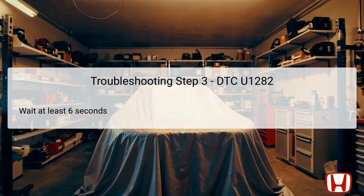In the third troubleshooting step for DTC U1282, it is important to wait for at least 6 seconds after switching the ignition back to on. This waiting period allows the onboard vehicle systems adequate time to initialize and establish all necessary communications. Swiftly moving on to the next checks without this pause can result in incomplete system readiness, which could yield misleading results in subsequent diagnostics. This waiting period significantly helps by ensuring that all electrical modules are functioning as intended.